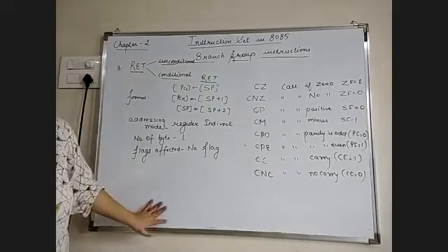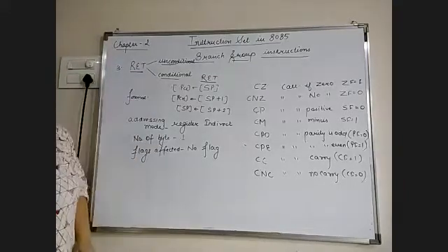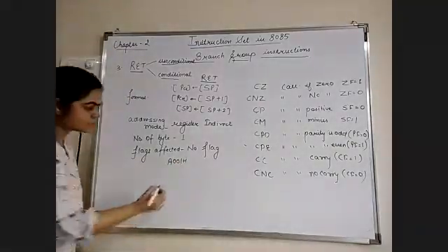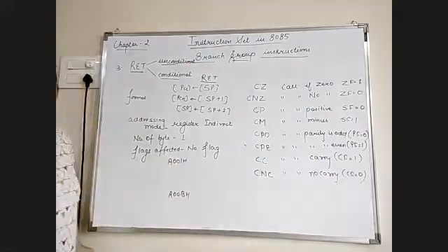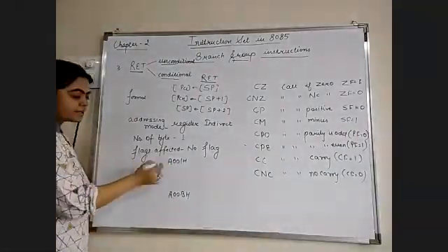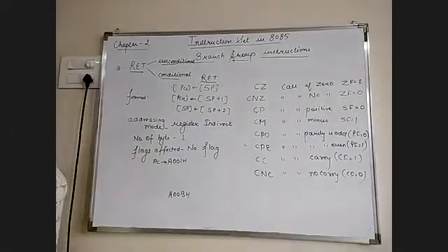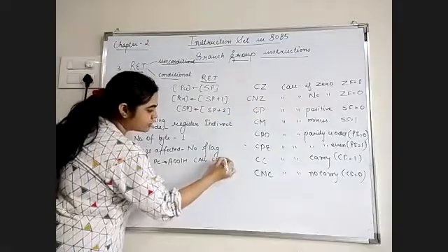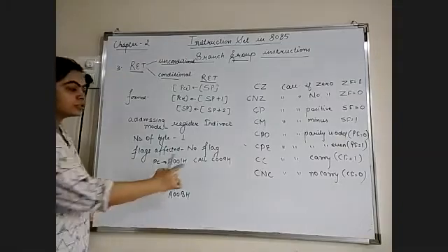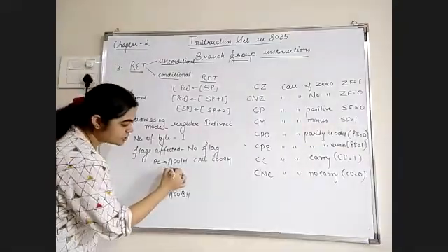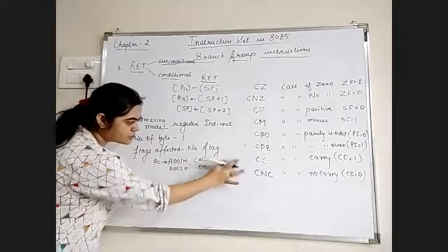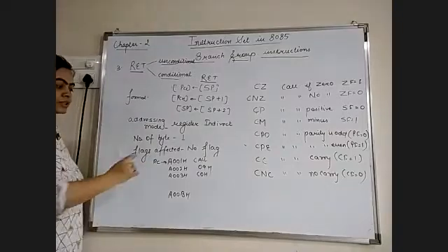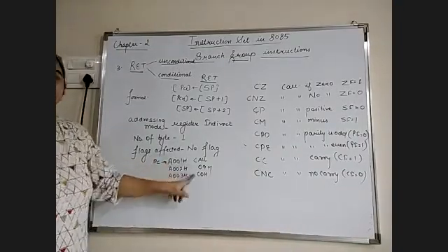Now we can see one more example, which is the combination of the call statement and the return statement. Suppose again our program starts from memory location A001H to A00BH. These are the memory locations occupied by the program, and initially the program counter is at location A001H, where we have the instruction CALL C009H. This instruction can occupy 3 addresses. At A002H we have the lower order byte 09, and at A003H we have the higher order byte, that is C0H.